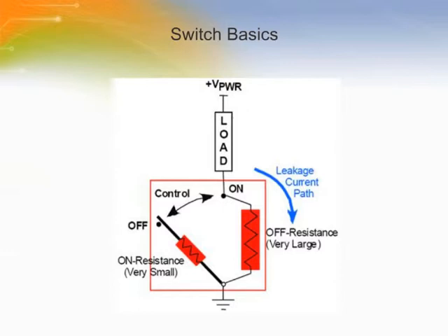When a switch is turned on, the switch will heat up. The heat is generated as a result of the current flowing through the inherent on resistance of the switch. Heating represents lost system energy and is sought to be minimized by making the switch on resistance as low as economically possible. When a switch is turned off, no current should flow. In practice, a very minute amount of current will flow around the switch as a result of leakage current paths having very high resistances. It again gives rise to heating and represents lost system energy. Good switches will exhibit many megohms of off resistance.